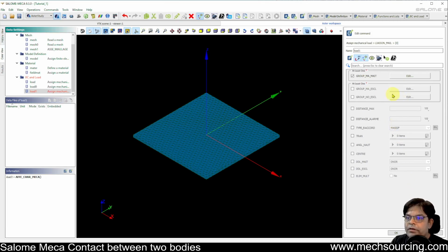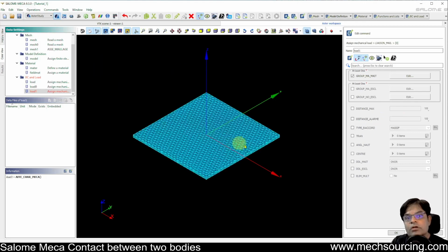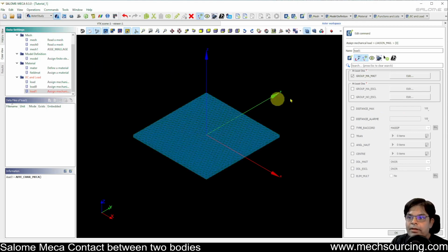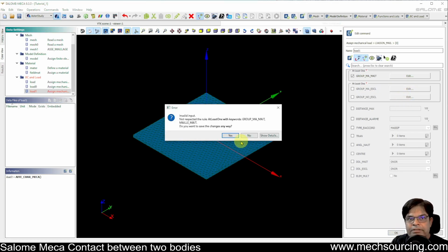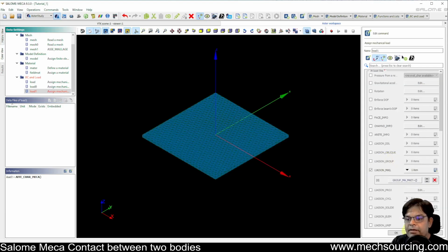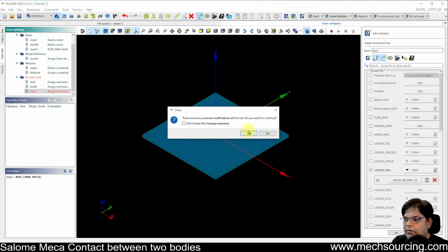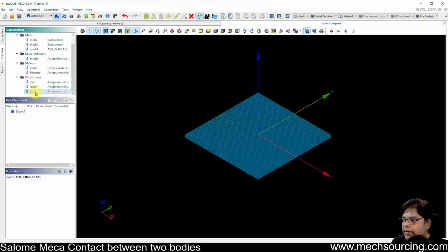And how we do it, that we need to do again by going to the geometry module and creating the volume elements. So I am choosing the volume elements as a frame, as a master element. So I will just close this. You will see it in red. Whichever detail is pending or not available will show in red.